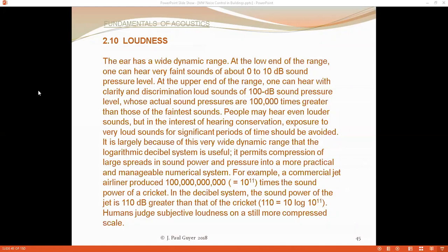And you have set your sound level meter, the ABC knob, on the A setting, and that will result in the sound level meter measuring the sound in a manner that is most representative of a human ear.